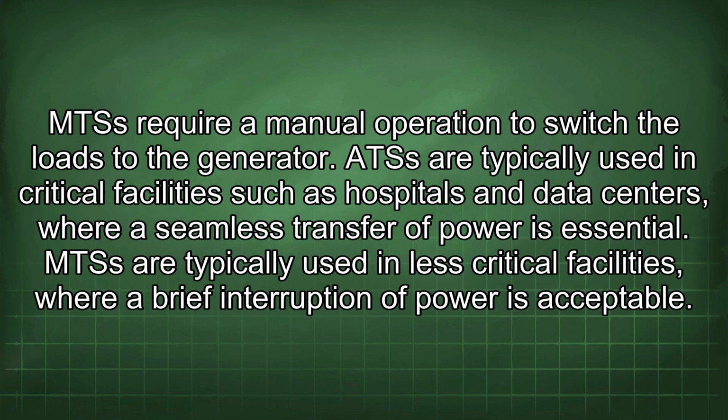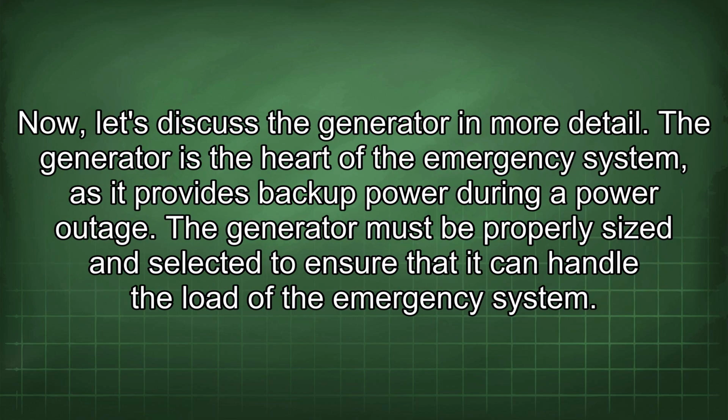ATS are typically used in critical facilities such as hospitals and data centers, where a seamless transfer of power is essential. MTS are typically used in less critical facilities, where a brief interruption of power is acceptable. Now, let's discuss the generator in more detail.